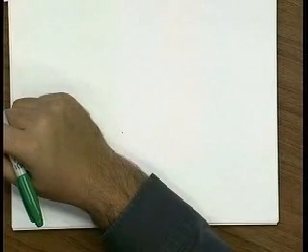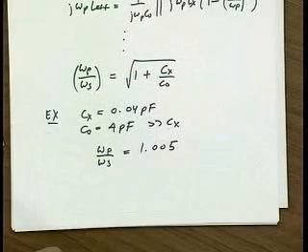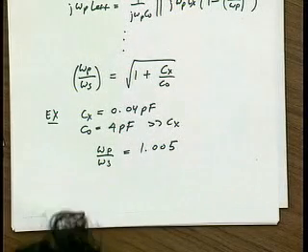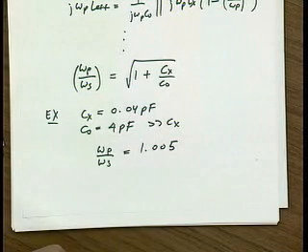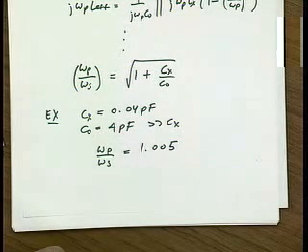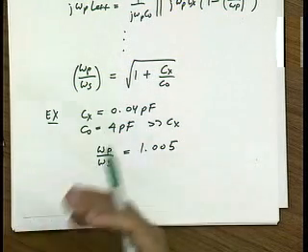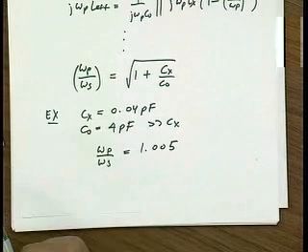No, but just to go back, so with the capacitors I attach, basically, I can choose any frequency between omega p and omega s. That's right. Without any difference in, say, Q or anything with the oscillator. Yeah, because this is such a small range, the quality factor is going to change less than 1%, right?